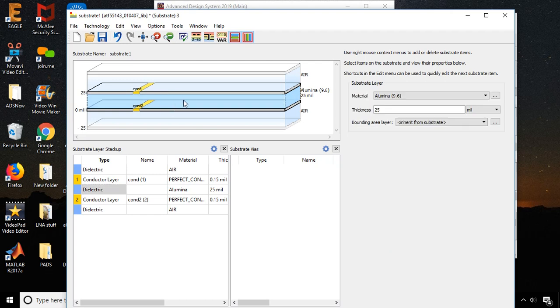Now, one more thing, we need to map a via. There's many different types of vias here. You've got a semiconductor via, dielectric via, all of these. These could be used, for example, on a chip design, where you would design a low noise amplifier chip, but mine's not a chip, it's PCB. What I'm trying to do really is just conduct the transmission line to the ground. That's all.